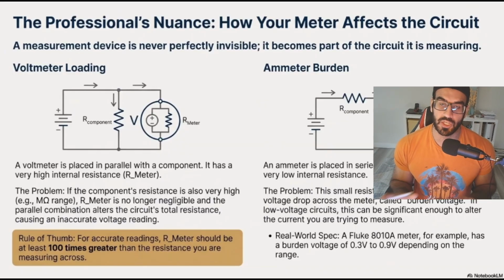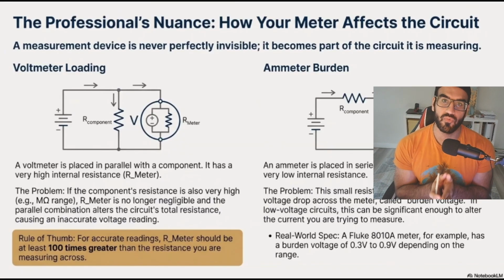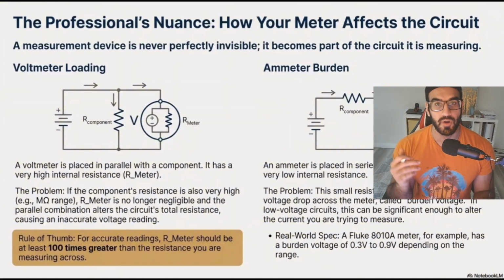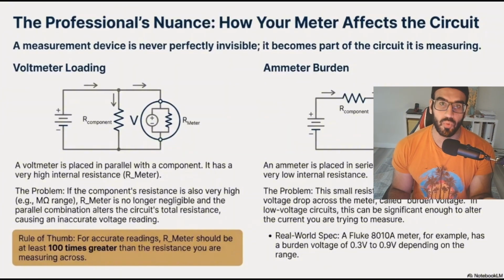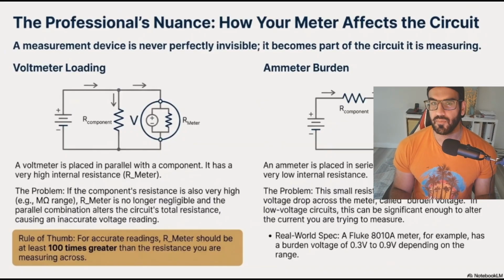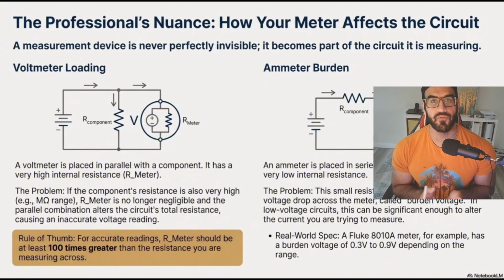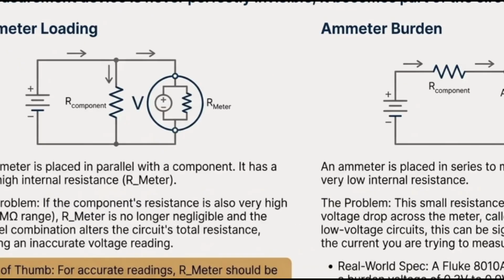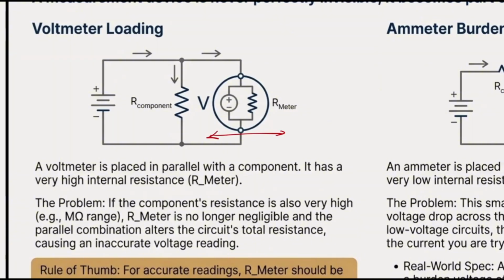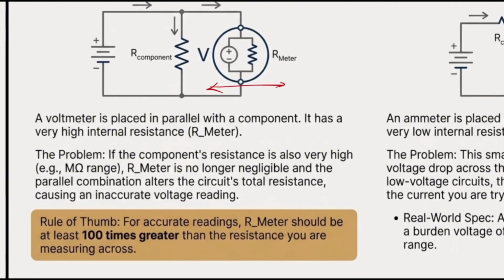But as we just mentioned, we would like my voltmeter not to have any effect on the system. But in the second option, when you have 2 mega ohm, the voltage source sees that something happened to my total resistance. My total resistance is somehow decreased. So I have to inject more current and everything would collapse. So at this point, it is very important when you connect your resistance to your voltmeter, make sure that the resistance inside your voltmeter is at least 100 times greater than your resistance itself, right?